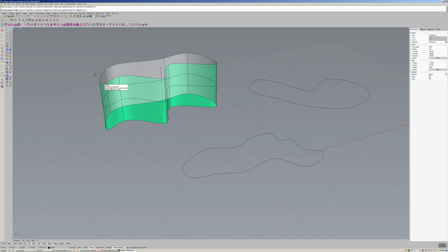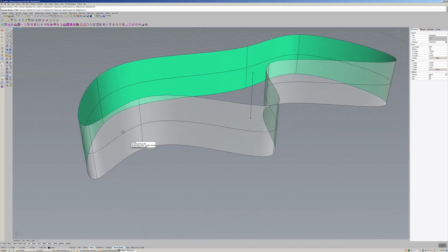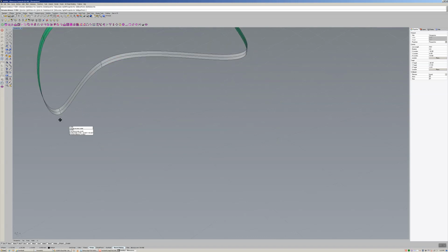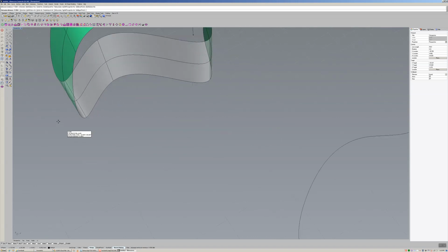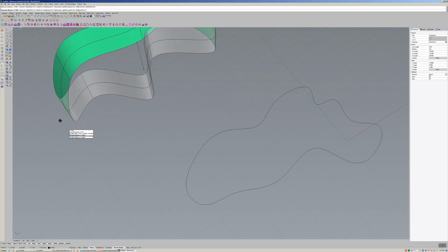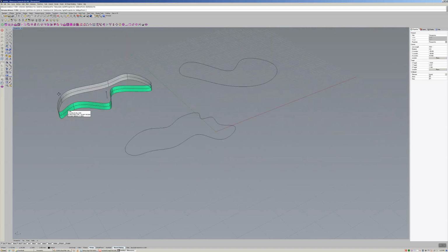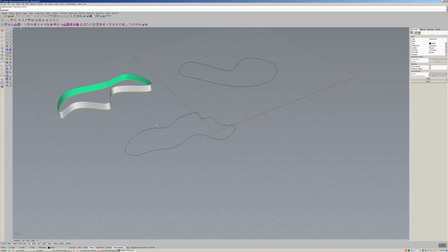Now, each one of these little boxes, if you zoom in, you have a big box, which is 10 millimeters. But each little small box is 1 millimeter. So I have it set for millimeters. You could do inches, you can do feet, you could do whatever. But in jewelry, we work in millimeters. So instead of eyeballing how big it is and guessing where 2 millimeters is, I'm going to enter 2, hit enter. That's now 2 millimeters.